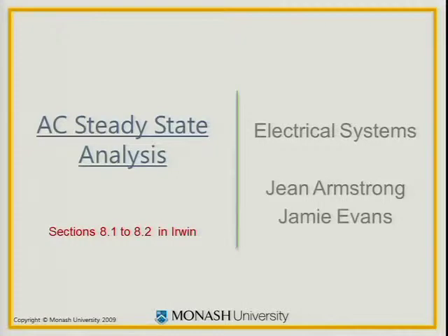Why might that be the case? Well, think about it. If you've got sinusoidal sources, how do you specify a sinusoid? Well, it's amplitude and its phase as well as its frequency. It'll turn out that the frequency doesn't matter, it's the same everywhere, so that we have to keep track of amplitude and phase of currents and voltages. What's a simple way to keep track of an amplitude and a phase? A complex number. Essentially what it gives us, an amplitude and a phase. So that's what we're leading to this week.